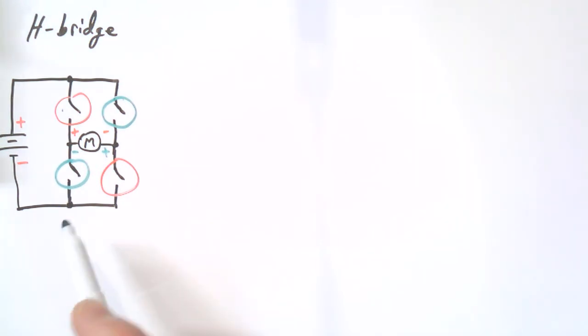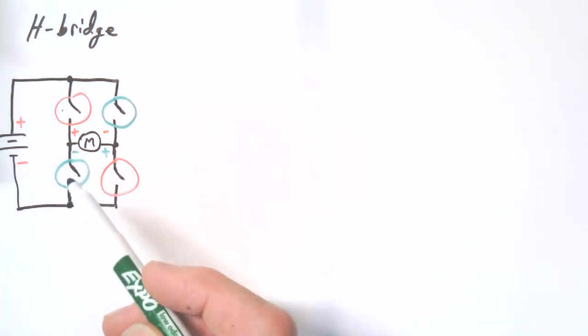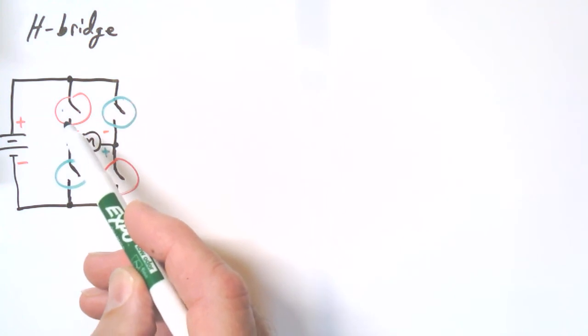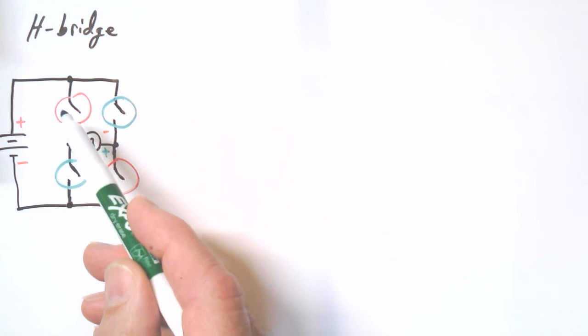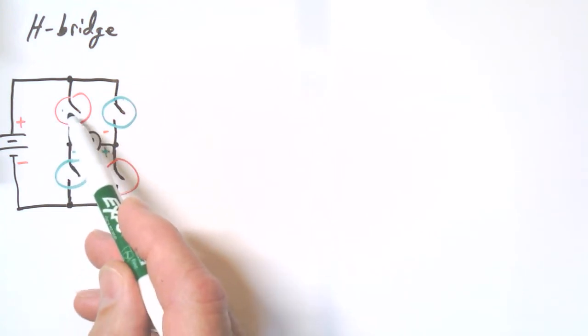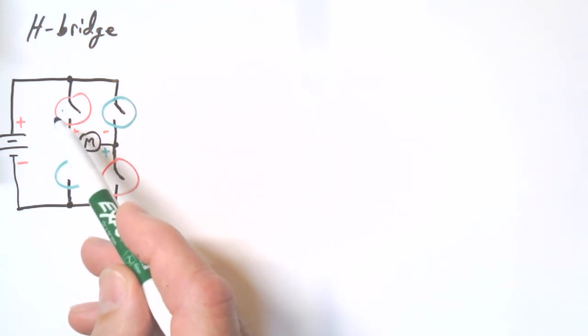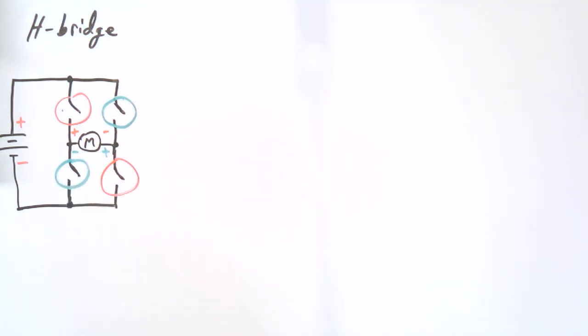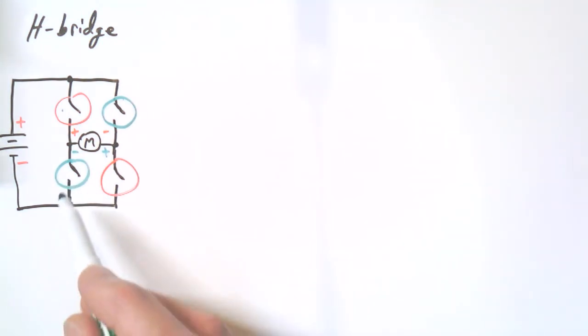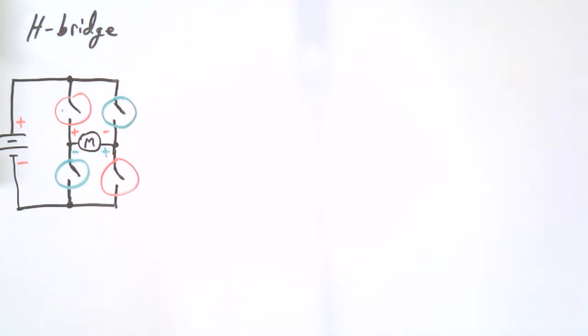If you're using transistors, it is tricky, sometimes, for example, if you're switching polarity, to get this transistor off before this transistor turns on and actually not have any split second where they would both be on for a fraction of a second.